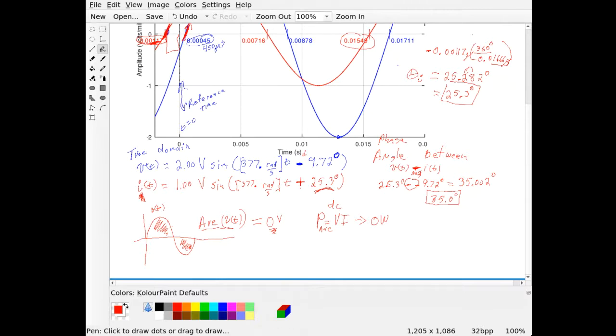I did talk about this last week, but I want to go through it again because it's very, very important, and I want to reinforce this. So what we do is create an effective voltage. If we have our waveform here and we try to take the average to determine the average power, that doesn't work. So what we're going to do is square our voltage.